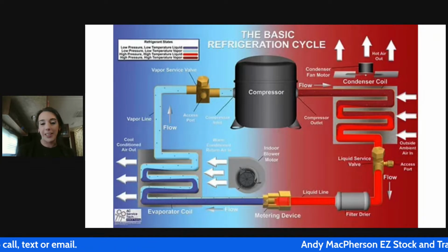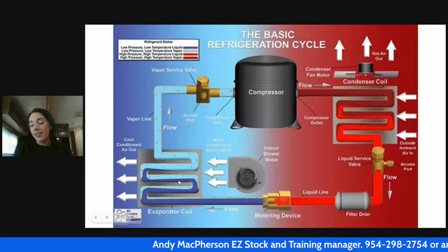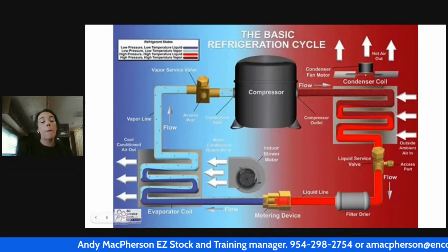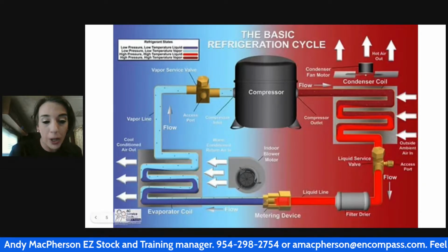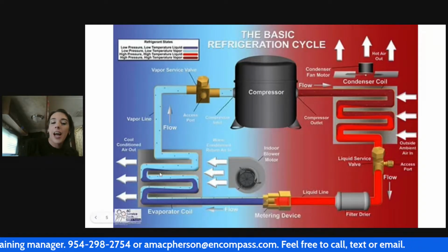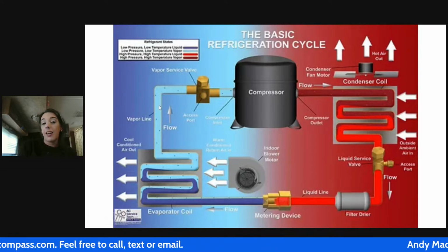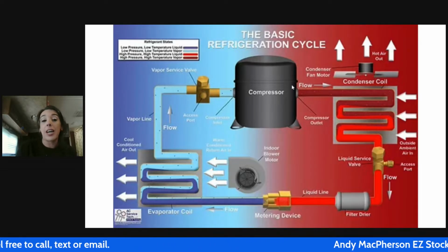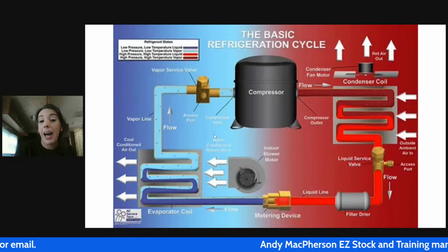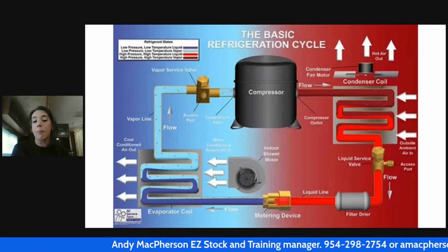Something is happening. That's why we were called there, right? So if I instead were to see, say, a 57-degree evaporator, I can definitely tell that this phase change is going to be happening closer to my outlet. Now, my outlet goes directly to my compressor. I do not want liquid there, but it happens so often because we don't know how to read our temperatures. We don't know what our temperatures mean.